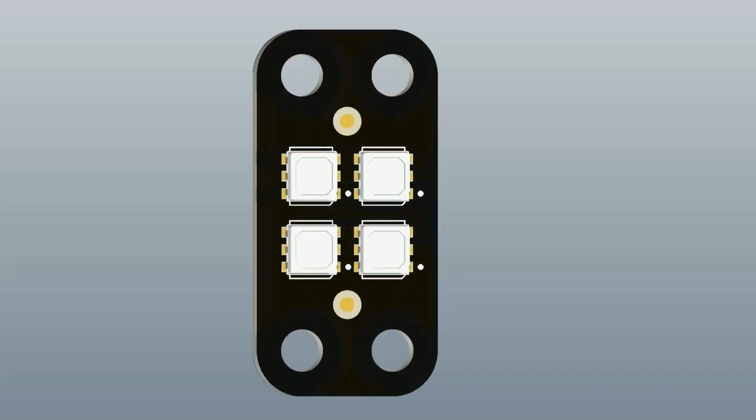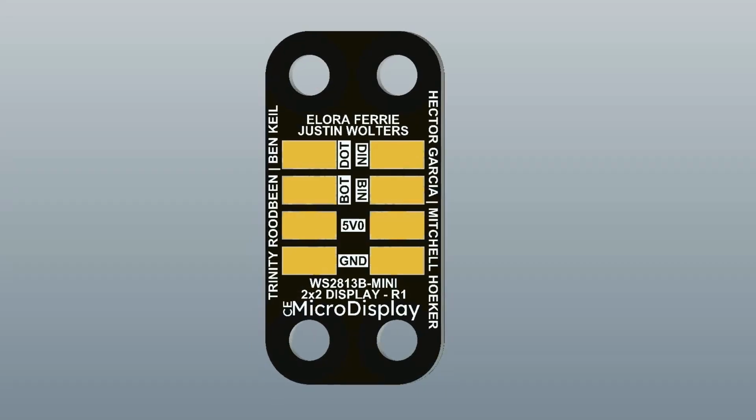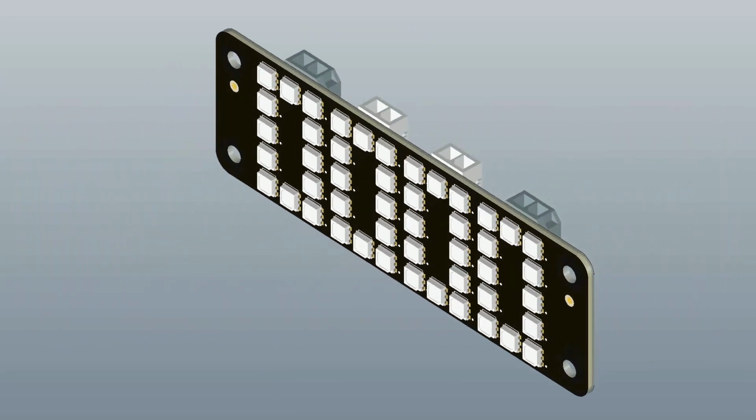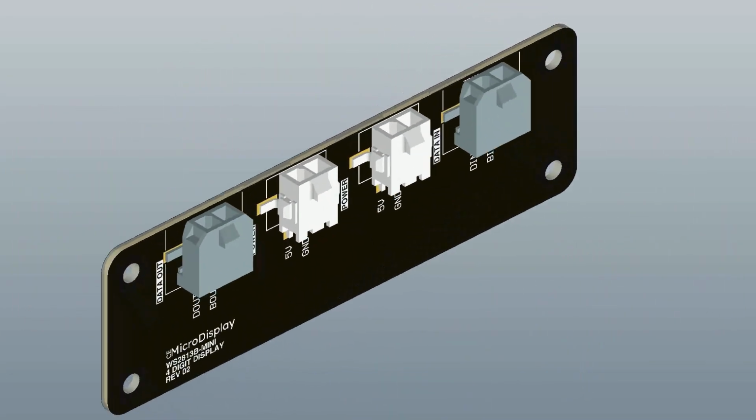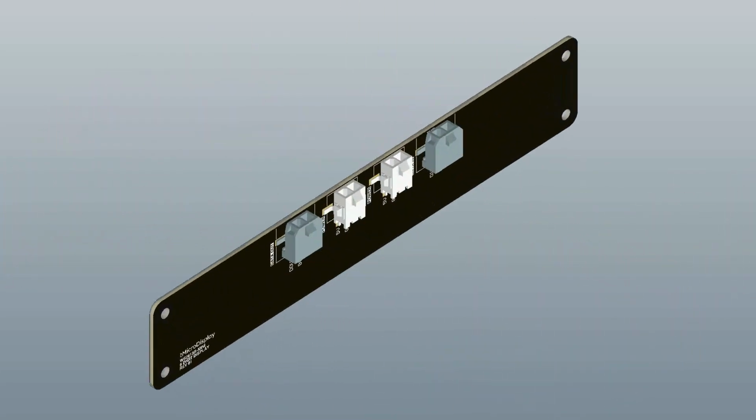Electrically, design was split into 4 systems: the power PCB, our display boards, the system wiring, as well as a power supply for the overall unit. For this project, we decided we needed to make our own custom display LEDs, as the ones on the market, such as 7 segments, did not meet our needs. We designed a total of 3 display boards: a 2x2 display board meant to represent single-bit values, either on or off, as well as a 4-digit and 8-digit display board meant to represent numerical binary 1 or 0 values.